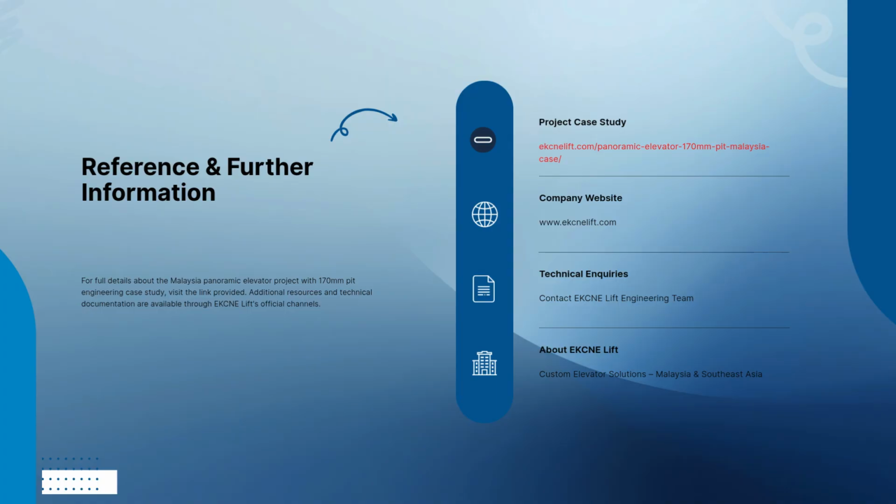Conclusion: this Malaysia project shows a simple but important lesson. A panoramic villa elevator is not only a design feature. It must solve pit depth, structural fixing, voltage stability, maintenance needs, and emergency safety at the same time.